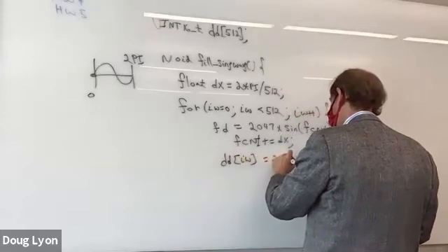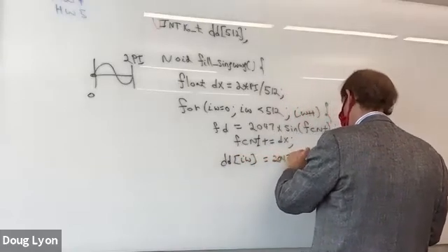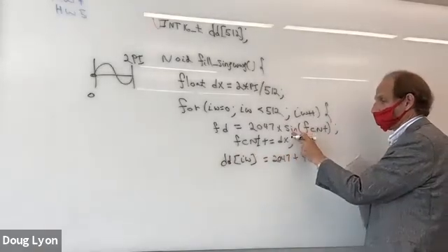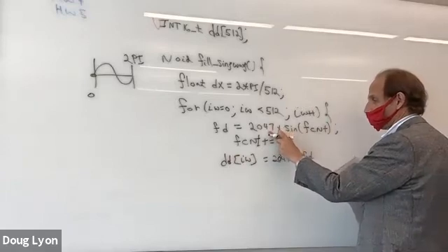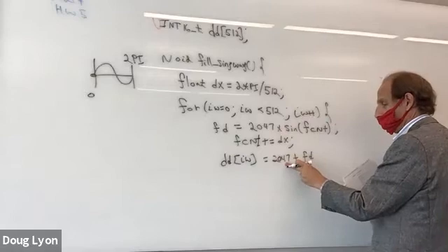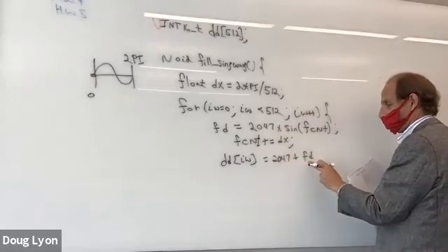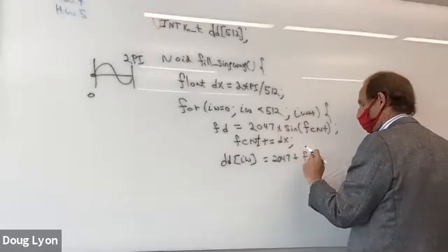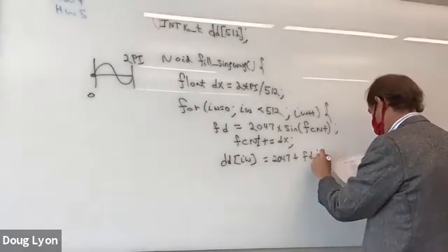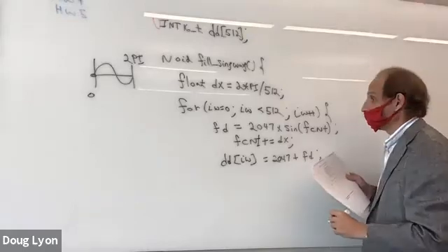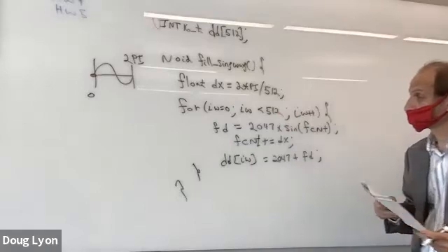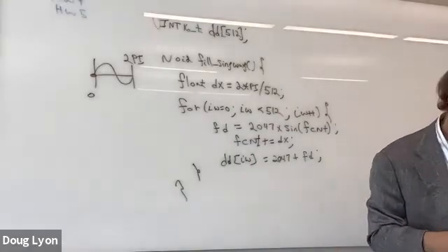And then what you want to do is set your output waveform, dd, is 2047 plus fd, right? Because sine is going from -1 to +1. Now it's going from minus 2047 to plus 2047. So we increment by 2047, and now it's going from 0 to 4095. And then that fills up the sine wave. Now it'll create a sine wave for you.